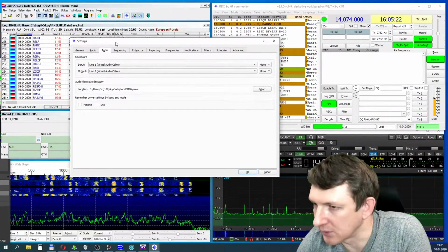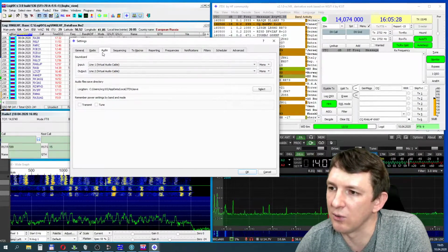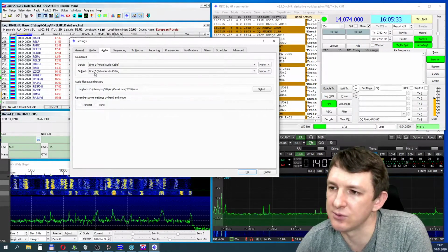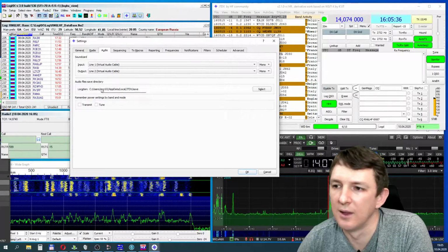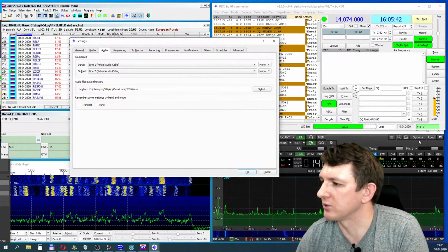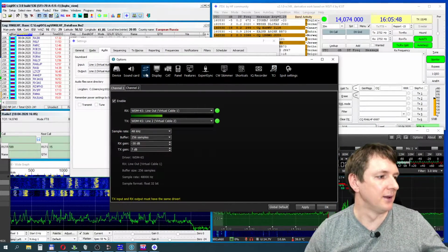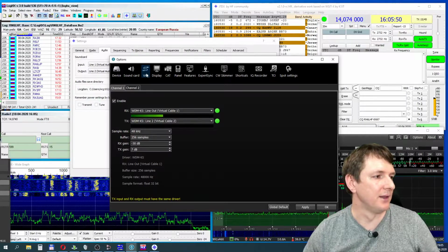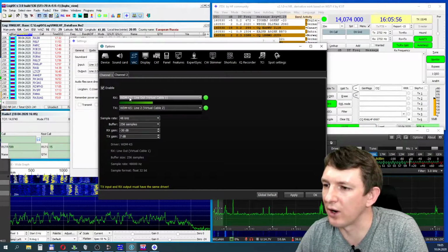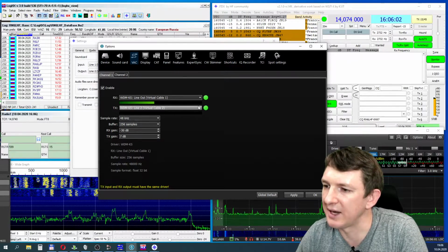Also audio connections. We should use two pairs in the audio tab. Input we can use line 1, output line 2. Input is used in receiving mode, line 2 can be used in the transmitting mode. In the SunSDR2 options you should use the VAC menu and use for RX mode cable 1 and for TX mode cable 2, line 2.